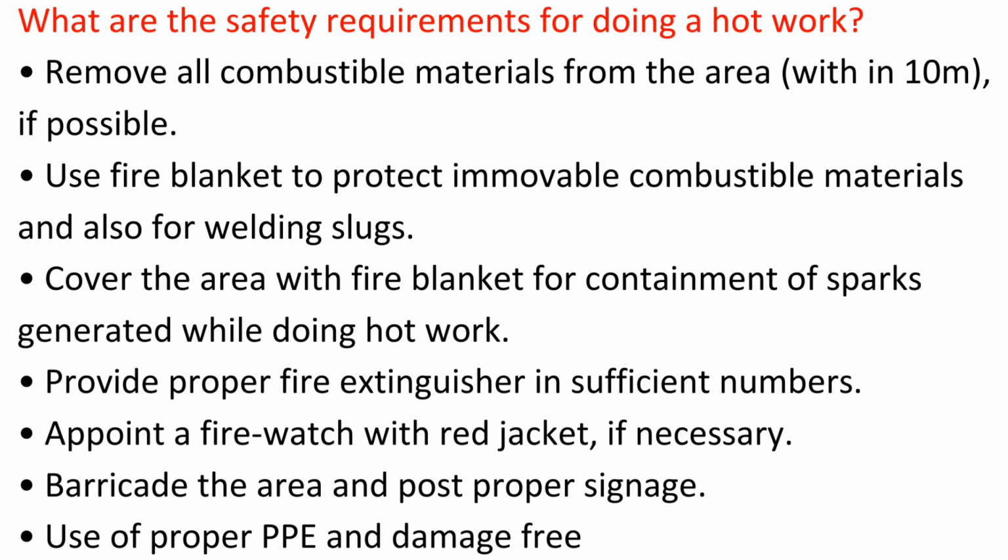Answer. Remove all combustible materials from the area, within 10 meters if possible. Use fire blanket to protect immovable combustible materials and also for welding slugs. Cover the area with fire blanket for containment of sparks generated while doing hot work.